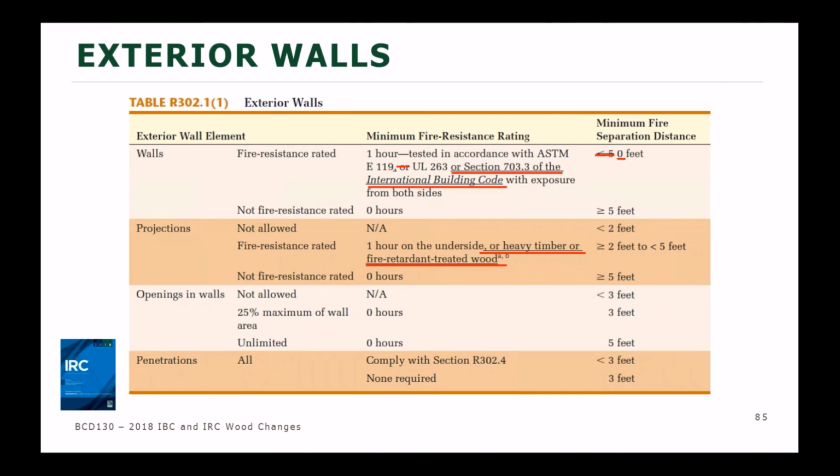There are also a couple of footnotes for this item that allow you to take some roof sheathing up into the roof above the exterior wall and basically protect everywhere from the wall inwards and allow that out to exterior area to be a sacrificial area. If you're up to 5 feet away from the lot line, then no fire resistance rating is required at all.